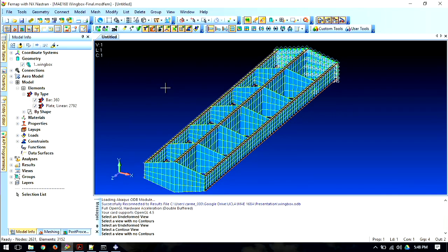And we have beam elements, right? I can represent this whole I-beam that you see here as one beam element, but I can't do that with a wing box. How am I going to connect the skin to it? How am I going to connect the ribs to it? I can't do that in this application, although it has its applications. So what I do is I take my I-beam section. I'll model the web as plate elements, so this is all plate here. And then my caps, I'll model them as rod elements, or I'll model them as beam elements if I really care about anything other than axial load going through those spar caps. Here, I threw in beam elements just because. Other than that, everything else is 2D plate elements.